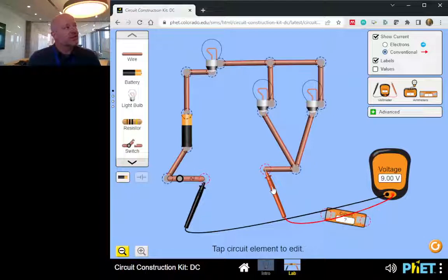One lab section I remember, we blew probably 9 fuses as different groups made the same mistake over and over again. It was ridiculous. So, big warning, it's embarrassing for the instructor when this happens. You don't want to blow a fuse on your voltmeter, so don't connect it like an ammeter.